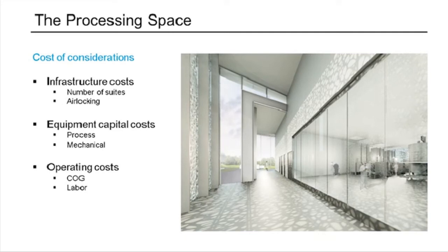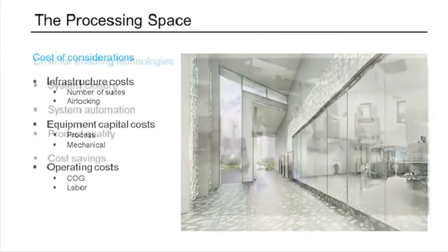But being cognizant of airlocks certainly, and philosophies around if your facility must be unidirectional flow or bidirectional flow, certainly bidirectional flow is going to reduce the number of airlocks and reduce that cost, reduce that number of spaces that must be sampled. And then again, things like HVAC, utilities, labor, those all go into your operational facility cost.